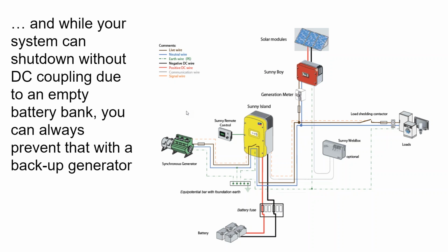But getting too caught up in the nuanced discussion between AC and DC coupling is kind of silly. Technically DC coupling should be cheaper, but the lack of product availability on those high voltage DC charge controllers makes it really kind of a wash from a cost perspective. So maybe down the road into the future, we'll see DC coupling become more popular. But right now, AC coupling is the more popular route to take.